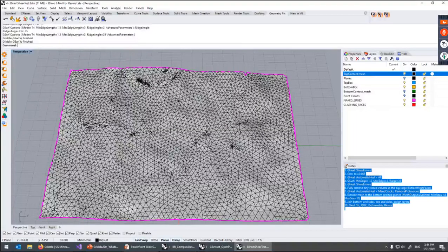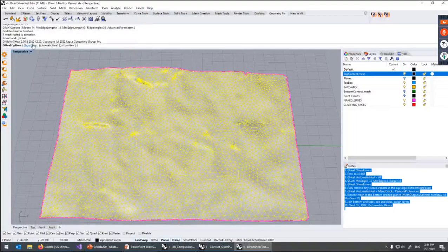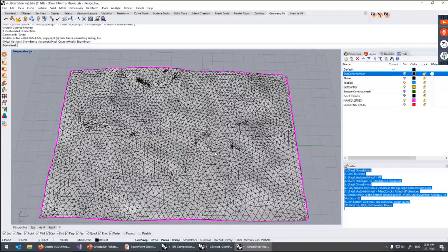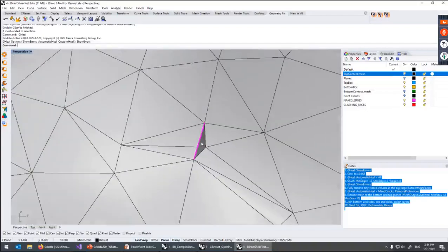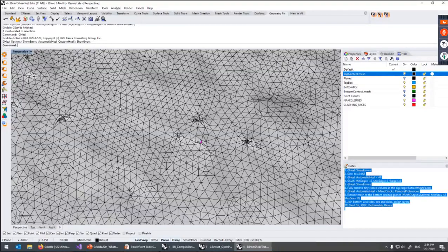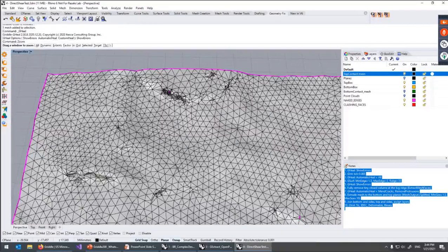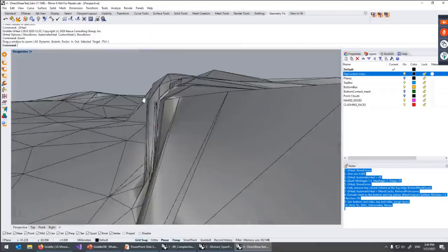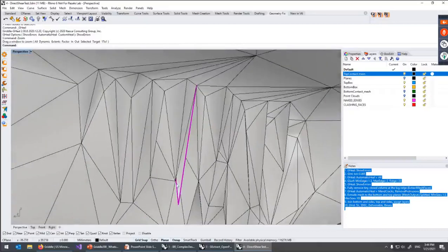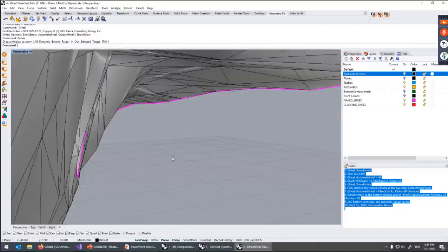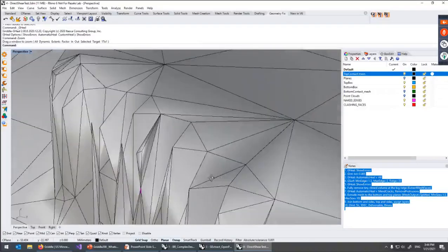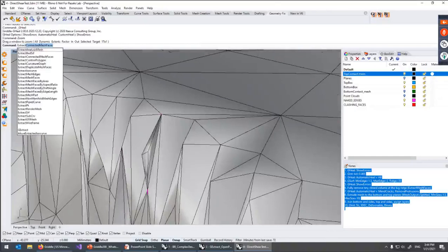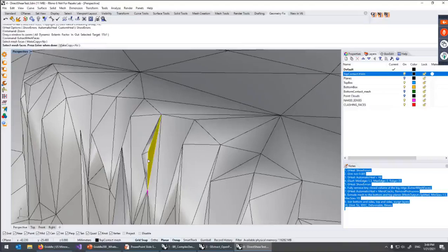We got a bit more uniform mesh, but unfortunately this mesh contains some new problems now. If I check for problems now, we can see that there's some extra face that appeared here, and there's something happening over here. So let me zoom to this area. You can see that this area is actually a ridge, and the face is on the other side of this ridge. It's this extra face that's not connected to anything. And there's also this extra little volume here. So let me actually remove this volume first by removing faces.